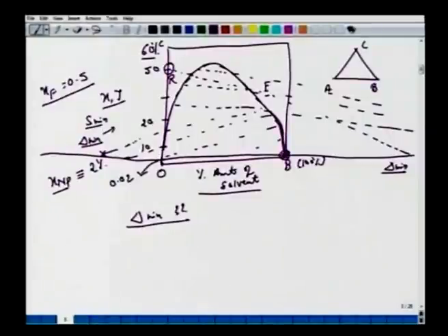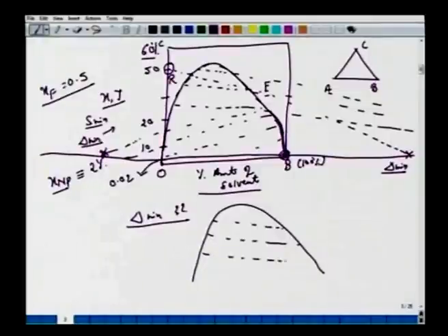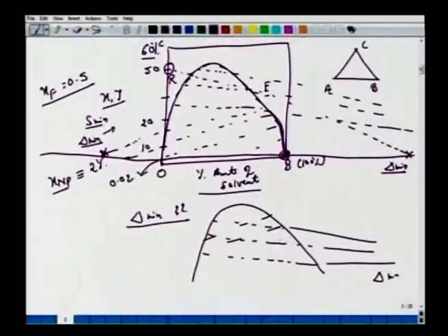So in principle we can have two scenarios. Now I can recall previous examples. We had the equilibrium curve, and all the tie lines were in one direction. In that case, if you extend through the feed, you have the delta min this way. If the tie lines are monotonically decreasing in one direction, you extend through the feed and have this delta min on the left hand side.